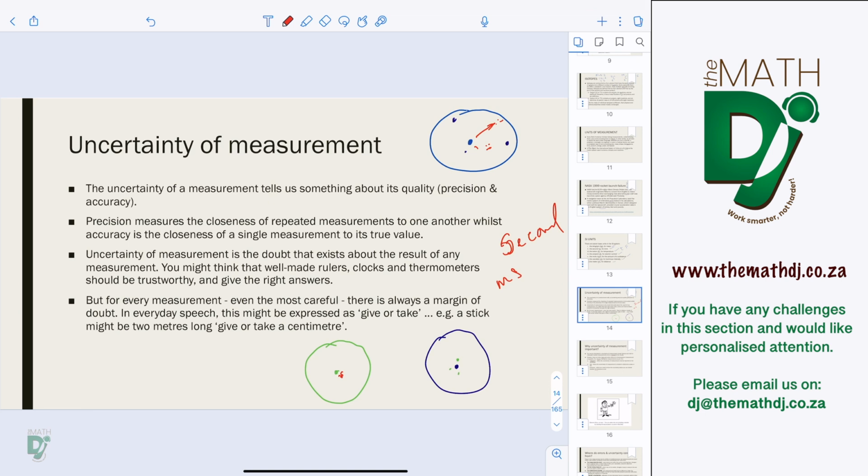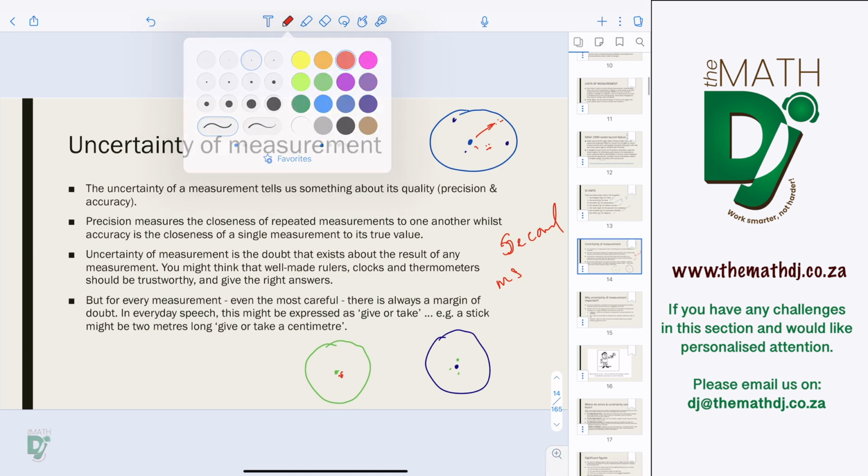That's why in the industry they want you to calibrate. Calibrate is when you use an instrument, with time it can give you different results which may not be accurate. So you need to calibrate to make sure that your measuring devices are still measuring whatever you want to measure accurately. That is under the quality department.